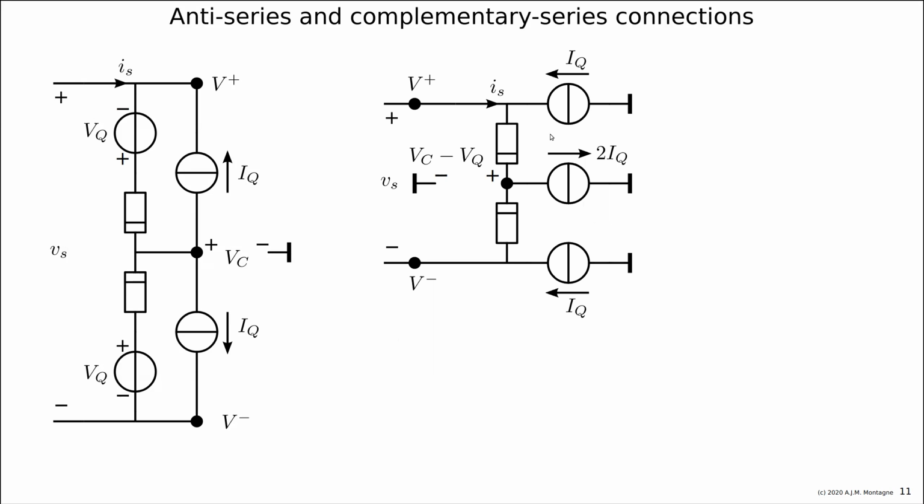And then you see basically that the bias voltage can be observed as the common mode voltage. That was already there, of course, on the common mode voltage at this node, because now we have eliminated VQ. So we changed the voltage VC after elimination of this VQ.